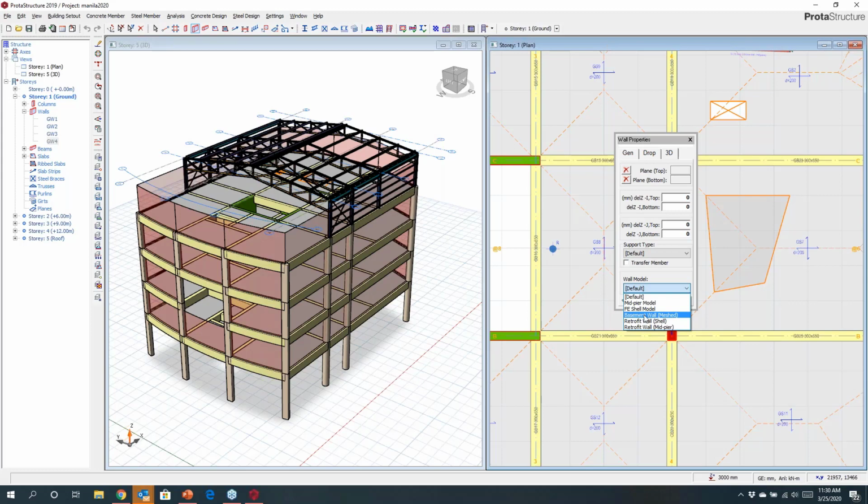This is where the basement mass would participate in the superstructure, or the building above wouldn't. And then the second analysis where the building above participates but the basement doesn't. And you would automatically have different R factors for those situations, and you can consider those in one analysis run within the software.